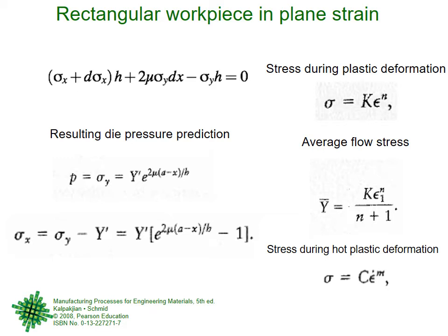But if there is any plastic deformation, and of course forging or any other are plastic deformation. Plastic deformation means you deform such that when you remove the force, the deformation is permanent, isn't it? If it was in the elastic range, you deform, it will deform, but when you remove the force, it will go back to the normal size, original shape, so no manufacturing will be done. But if you want the material to take the shape of the die and to remain in the shape of the die, then you have to be in the plastic region.